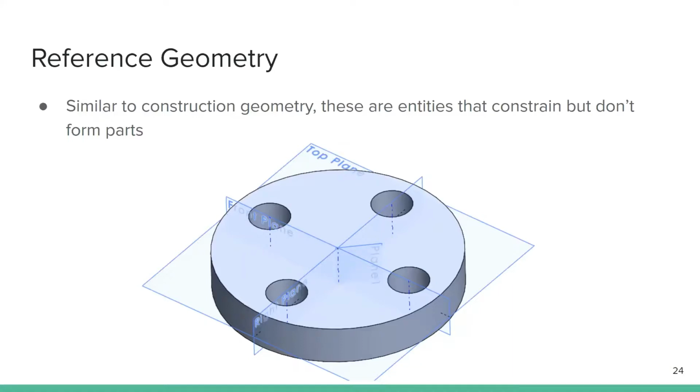If you made it in a sketch, it would exist inside that sketch, and that would be okay. You could still use it for pretty much everything you could use a reference geometry axis for, but it's better to use a reference geometry axis and put it where you want it, and then it'll be there forever afterwards when you need to tell SolidWorks to make things around that. And then planes, as I've mentioned before, I mean, that's common sense, right?